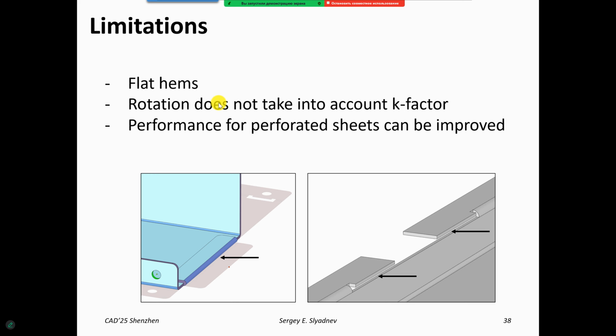And then, performance-wise, if we are working with perforated sheets, which are not uncommon at all, even the sparse meshes that we obtain from the CAD kernel happen to be too dense. So normally what we can do, and should do, is defeature smaller holes and cutouts before simulation, to simplify the simulation model. This is not very complicated to do, because we have the BREP model, and we can just cut off the corresponding features from the topology graph of the model.